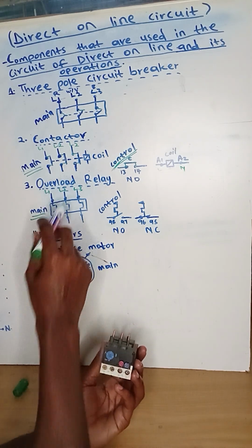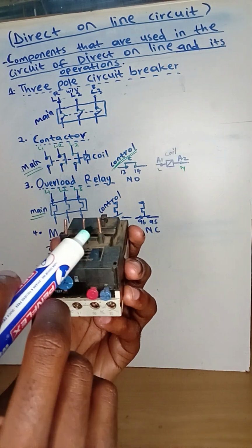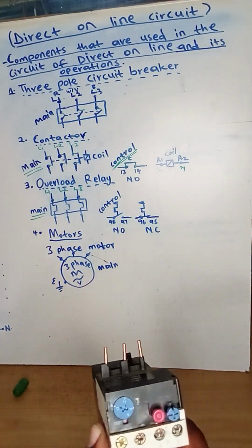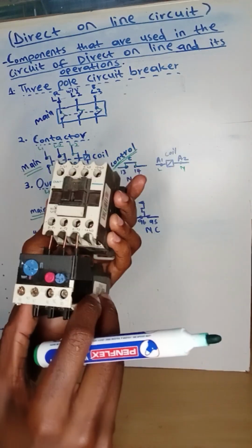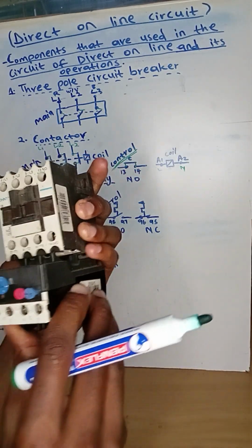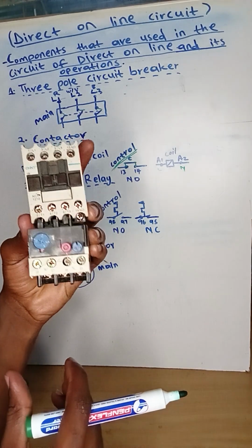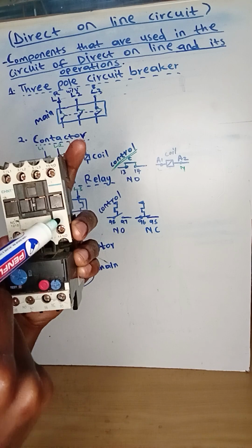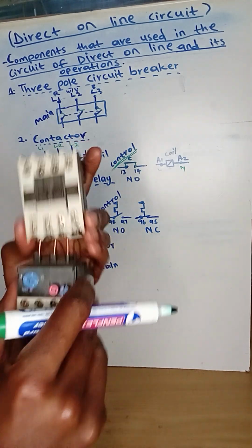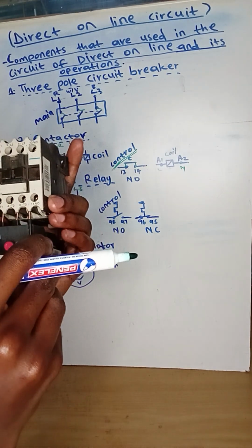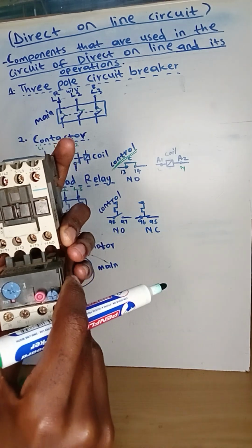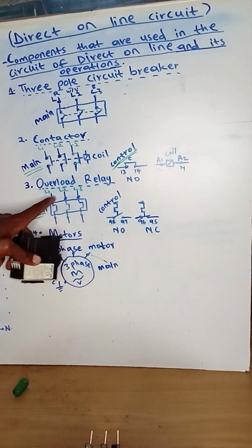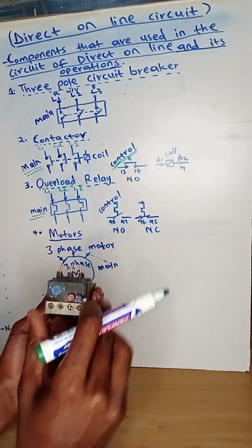And these 3 wires will be represented by these 3 pin points. So these 3 pin points, you will have to insert them under the contactor like this, only in T1, T2, and T3, but not from the last point, which is normally open. As you can see, it has 3 points, and those 3 points will only be inserted in T1, T2, and T3. So these 3 points represent these 3 wires. So I'm done with the top.